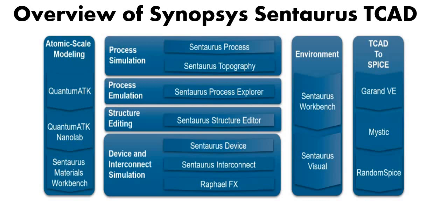So we can see that all the fabrication steps can be covered in the Sprocess simulation. Sentaurus Topography supports the modeling of topographical steps including etching, deposition, CMP and electroplating. So in conclusion, we can say process simulation is the tool in which we can easily fabricate the device in a virtual manner. So the next tool is process emulation.